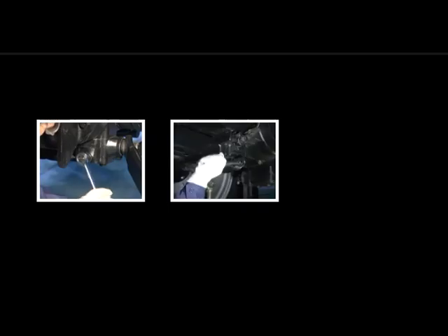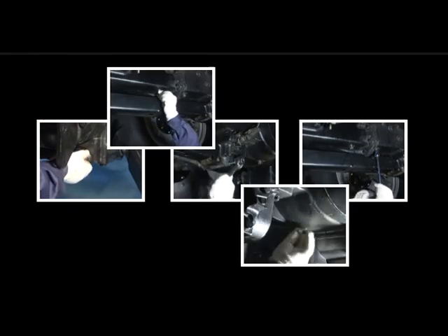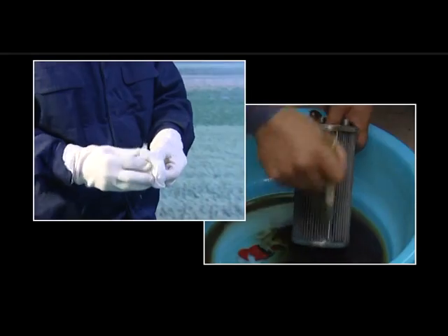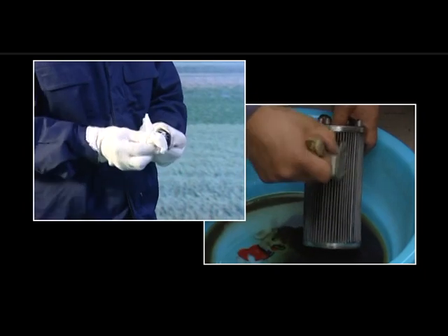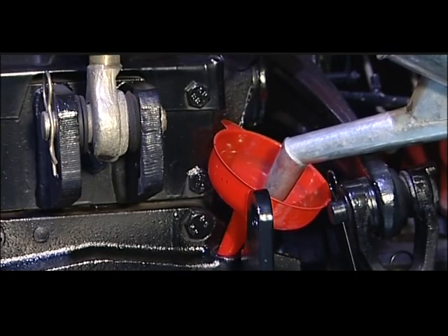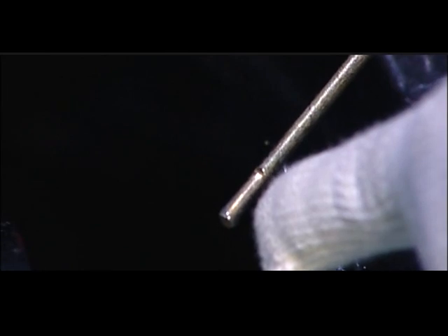Drain the lube oil in gearbox, lifter, and rear axle while it is hot. Clean the oil drain plug and all filters, then refill with new lube oil to specified level at all aggregates.